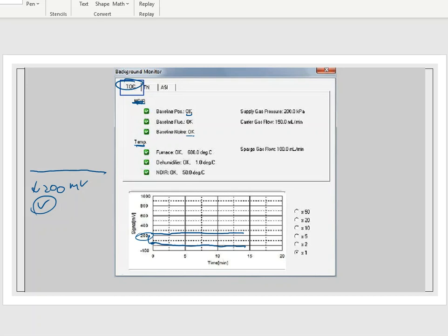However, over time, the NDIR could start to decompose if you're not keeping a routine maintenance schedule on it, if you're letting your halogen scrubber or your filter go bad, if something is causing a problem and it's starting to corrode the NDIR, then you're going to see a higher than normal millivolt signal. And when this goes over 200, it could be a very bad sign. So you would have to readjust the baseline. You would double check your NDIR, and you would readjust the baseline to get it back down to 0 whenever possible. Okay, so that's the issue with the detector.